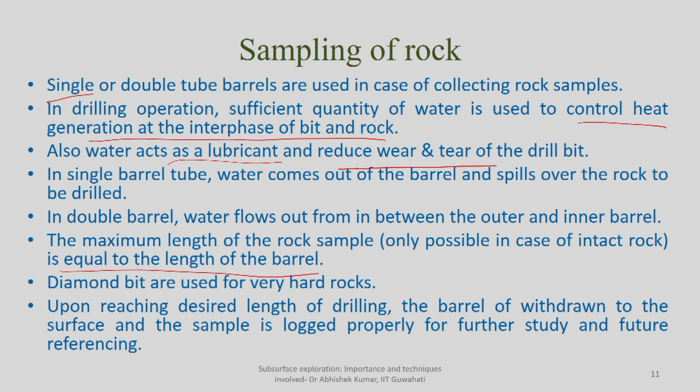We are talking about 2 barrel or 3 barrel. So these barrels will be used at the bottommost layer whenever you are collecting some rock samples. Whatever is the length of the barrel, that is the maximum length of the core you can actually drill. As I mentioned earlier also, the diamond drill bit you can use particularly for very hard medium, because if the medium is soft, then you can go for other kinds of drill bits, and a diamond bit may not be required.